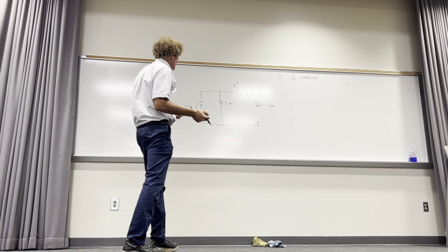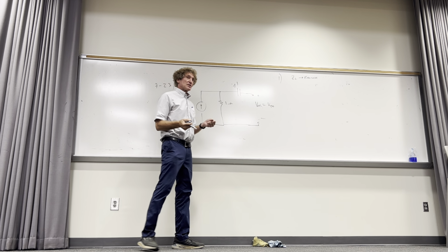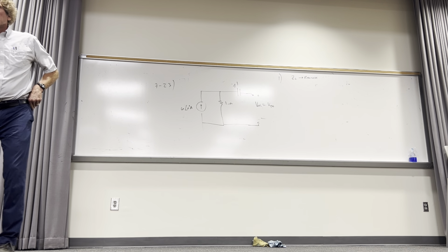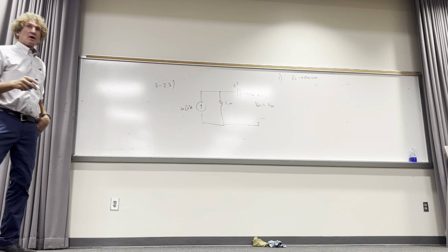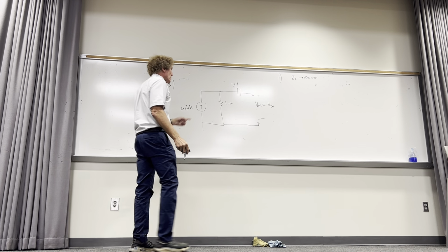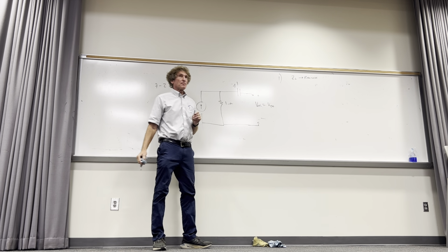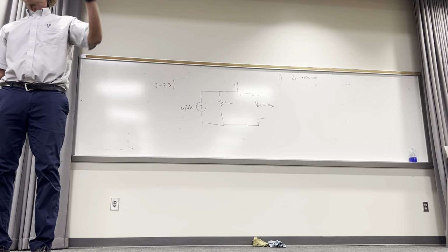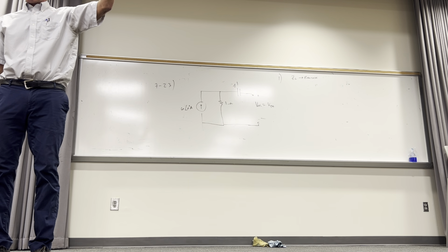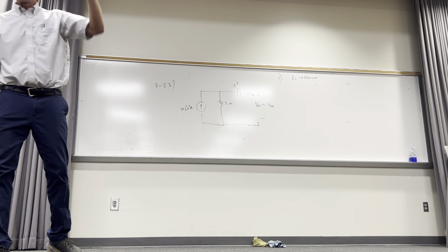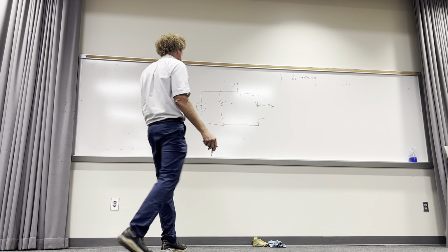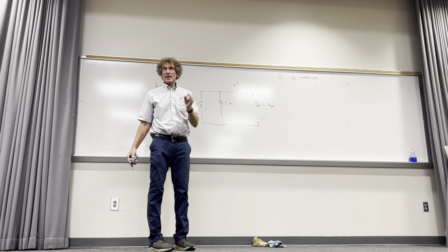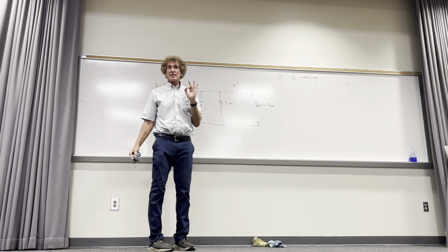Once I do that, how do I get this voltage? Just ask yourself this. If this was a quiz, how would you get it? Now, I'm going to ask an obvious question. How much current flows through that capacitor with the load removed? How many see it's zero? Nothing can flow, right? There's no way for the circuit to be complete. If nothing flows through here, what would the voltage be across that? Zero. Do you all follow me on that?